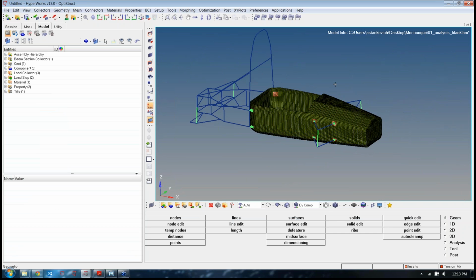After you run a free size, we'll start cutting up all these different layers into thinner layers and start realizing actual ply shapes that would be manufacturable. From there, the last step is a shuffle optimization, which basically tells you which order to lay all your plies up.